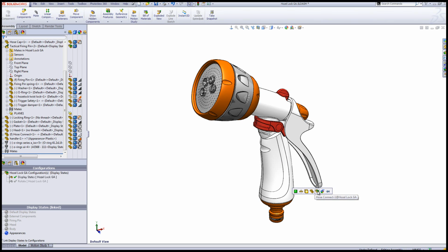Now this selection box is in hierarchy with component at the top, which is this one icon here, followed by face, then feature, then body, and finally part. Now I'll just apply it to component level, like so. And this will also apply a component level appearance in our appearance column in the display pane.